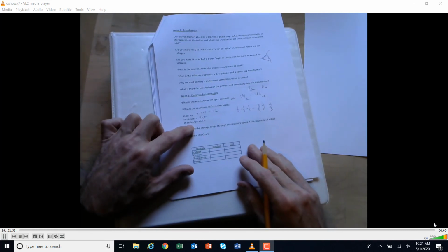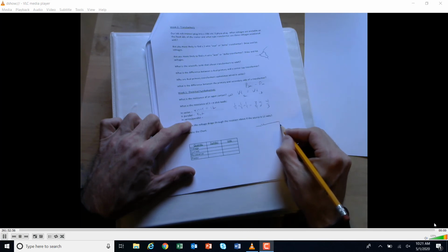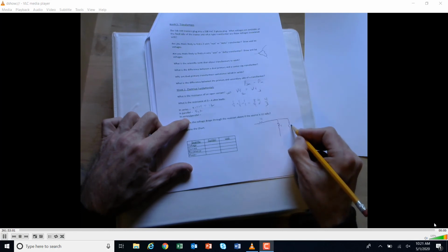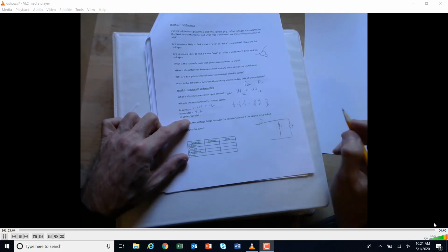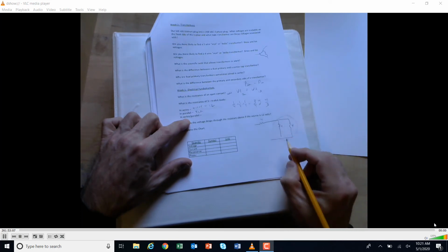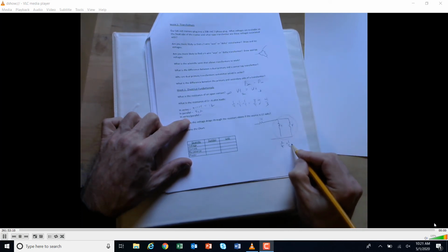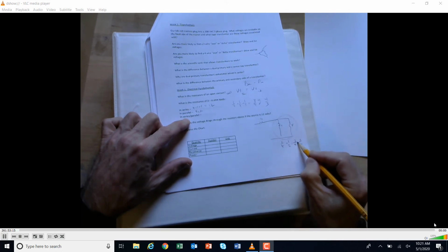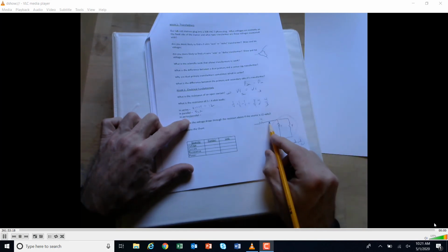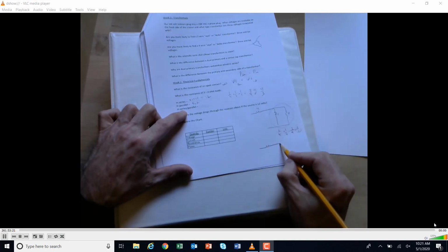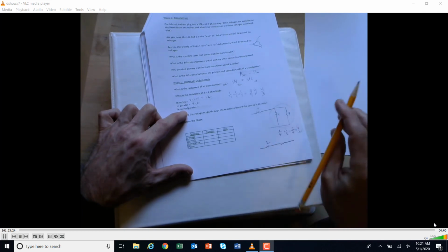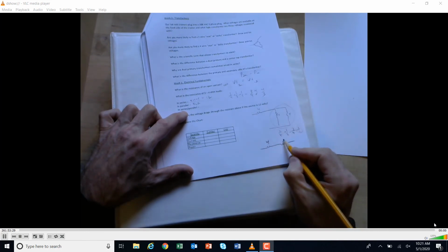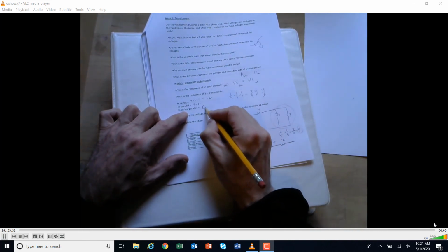And then in series parallel, that means we're going like this, I guess, where we have a 4, a 4, a 4. And so what do we need to do? Do our parallels first. 1 over 4 plus 1 over 4 equals 2 over 4. Flip it: 4 over 2. Well, 4 over 2 in my book is 2. So I'm going to simplify this and make it, excuse me, that would be 4. And these simplified into 2. So 4 plus 2 would be 6 ohms.